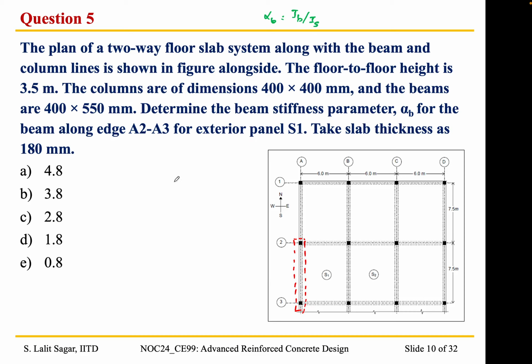Okay, so whenever we are considering the slab action, we need to consider the beam as a flanged beam.